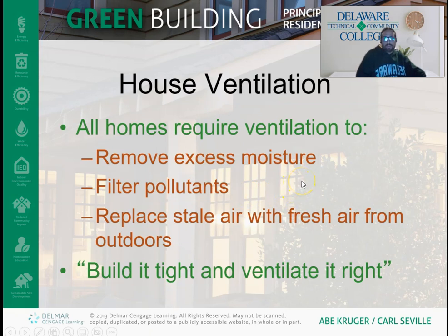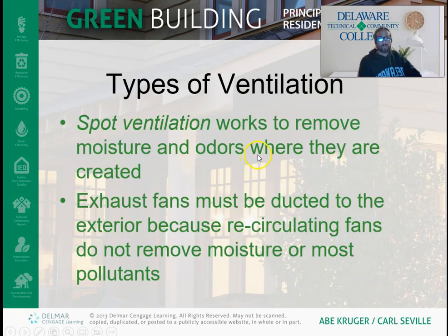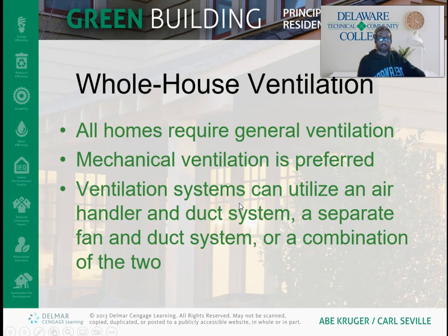We'll talk about ventilation and its importance. It's a little less important in most residential buildings, very important in commercial buildings, but you need fresh air for the people in the building. The tighter you make a building, the more important ventilation is, because if you have a really tightly sealed building, you're not going to get much fresh air in there naturally, so you need to add ventilation. Commercial buildings have codes and standards that require a certain amount of ventilation, and we'll do some calculations later. With residential buildings, it's a little less important, but some buildings do need ventilation. There are a couple of different kinds: spot ventilation, such as exhaust fans, and constant whole house ventilation as well.